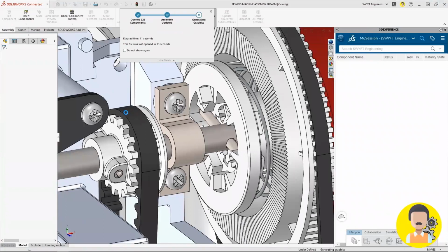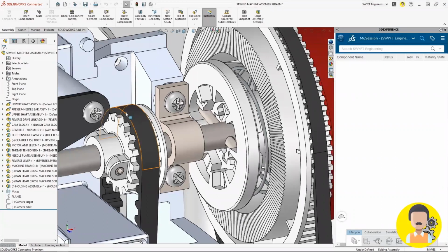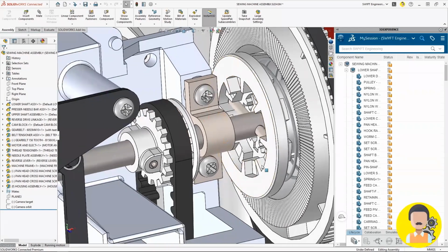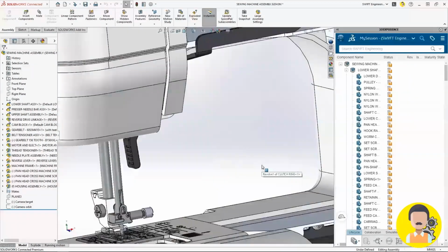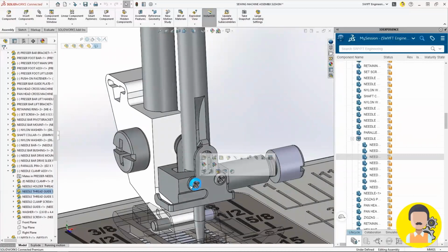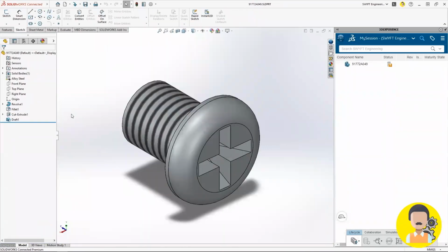Now, I did add a little bit more here, just as an FYI. If you work with, and you can't see it here, but these are in lightweight mode. If you work in lightweight mode, it might not update until it's resolved. So Lucas pans over to this component here, and it still has the old name. Oh, there it is. You can see that's in lightweight mode. As soon as that's opened up, though, it will update. So that's something to be aware of with lightweight mode. And if you're working with renaming components, make sure you resolve components to see all those changes.